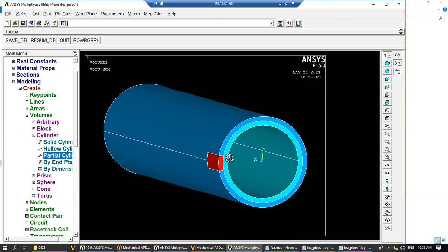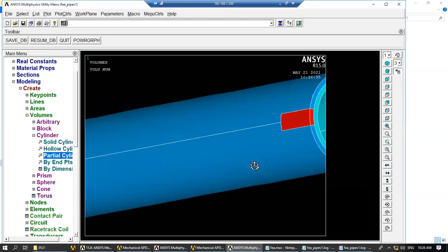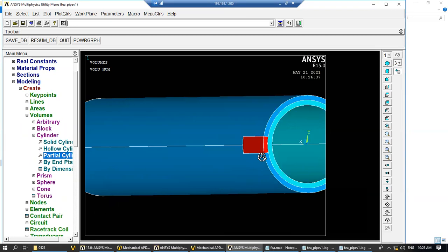Okay, then let me see. I will try to mesh this model now to see if we can have it. But what I did before in the slide is, for this part, I made more separation of this cylinder. And also in this line, I made it like this, okay? The idea to have this different division of geometry is just to have a better connection of element size here or there.